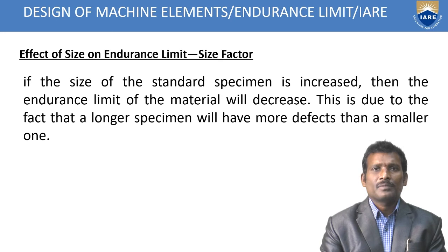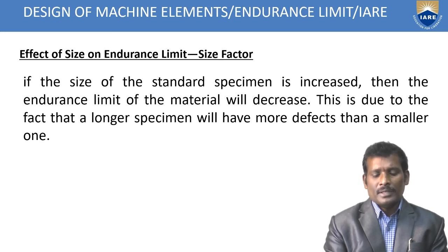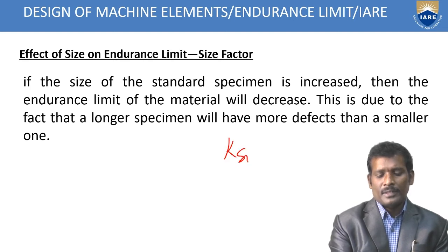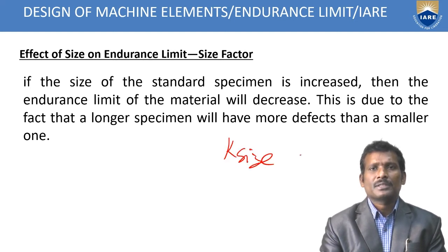Next one is the effect of size on endurance limit, the size factor. We can represent the size factor as K size. If the size of the standard specimen is increased, then the endurance limit of the material will decrease. When the overall dimensions of the component are increased, the endurance limit also will decrease, not increase. This is due to the fact that a longer specimen will have more defects than a smaller one.